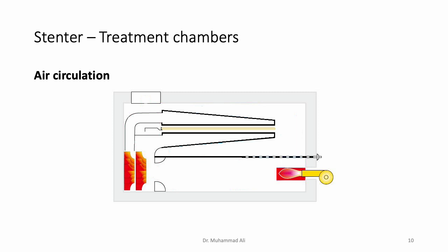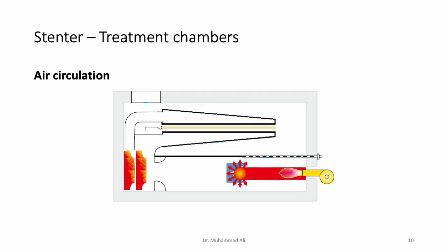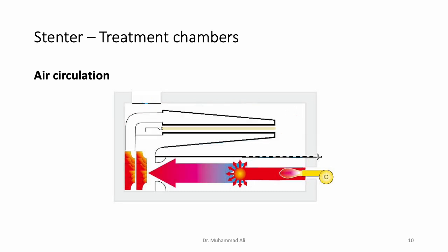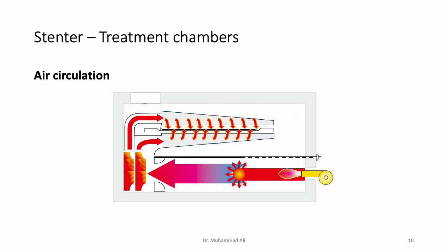Let's consider the example of direct gas heating, in which case a natural gas burner is actually turned on in the heating chamber. As this natural gas burner produces combustion gases in the heating chamber, the air inside the chamber is heated up. This air is drawn in axially by centrifugal fans, which then blow this hot air into separate upper and lower ducts. As the fabric is placed in between these two ducts, air comes in contact on both sides of the fabric, and this is where heat exchange with the fabric takes place.